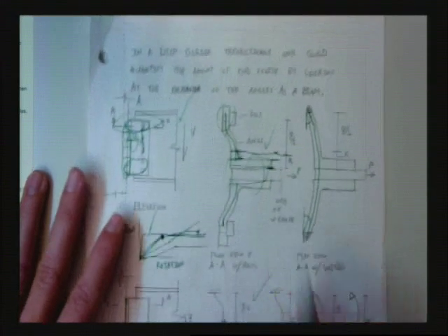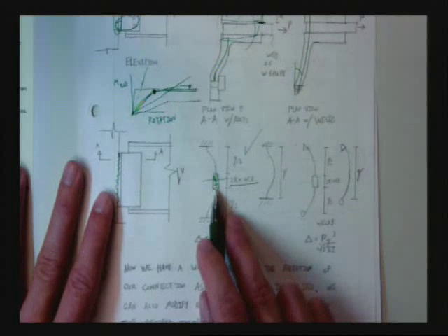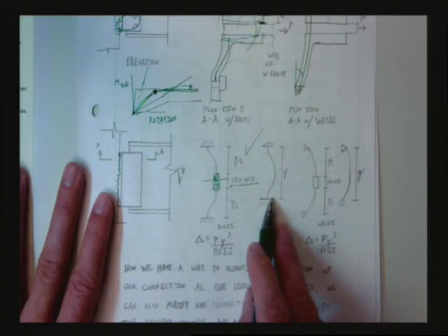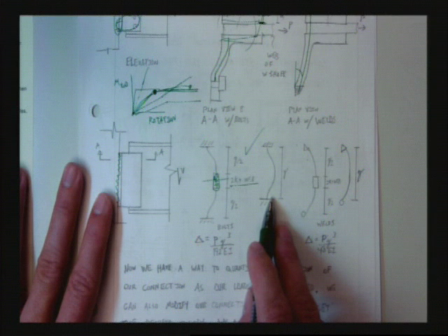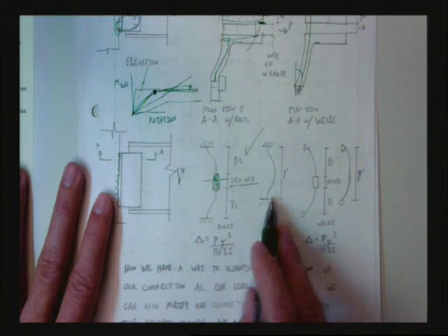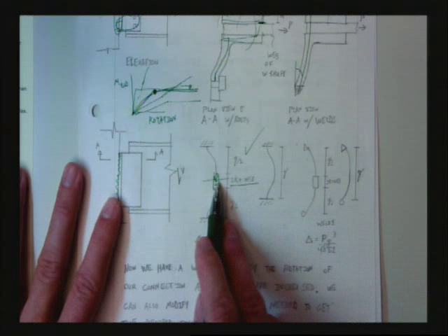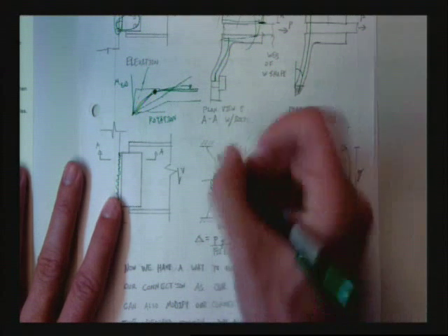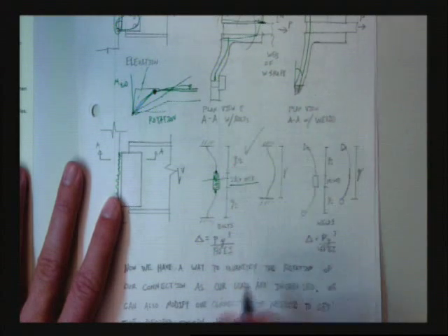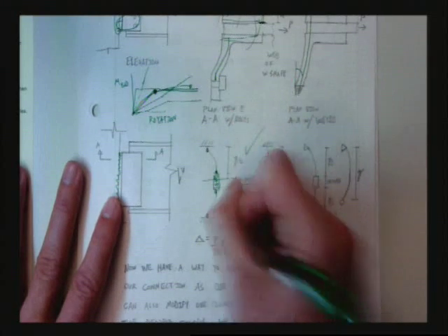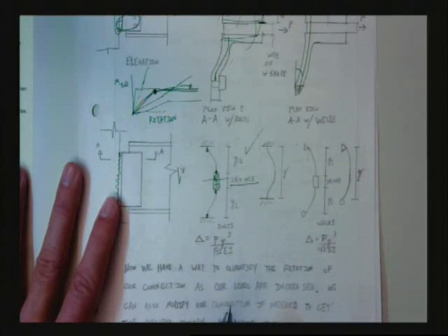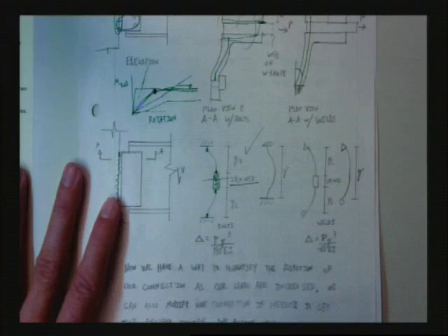Okay, so we got this thickness, and we're going to imagine like it's not there. We're going to simplify the problem even further to this. How can we do that? Is that conservative? Is that okay to do? It is. The reason why is things that are infinitely stiff, they're pretty strong, aren't they? So we wouldn't expect any yielding to happen here, would we? We'd expect yielding to happen here and here, or here and here, right? And we care about deflection, don't we?